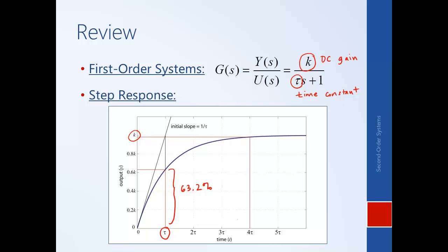Looking at this step response, its character matches what we would expect based on what we've learned earlier in the course. In particular, we've learned that the output of a dynamic system is determined by the type of forcing input and the natural response of the system. So in this case, we're forcing the system with a step or a constant, so we would expect the output to have a constant in it. And since we have a single pole that must be real, we would expect the natural response to be exponential decay. And that's what we get here.